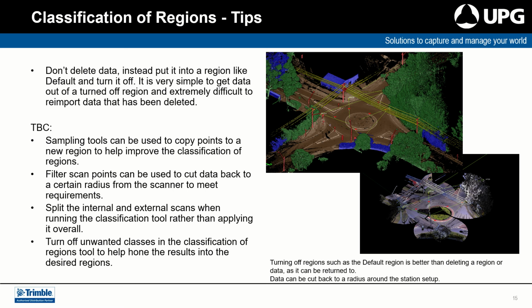Again, as I mentioned earlier, splitting the internal and external scans when running the classification tool is recommended rather than applying it overall. So that comes into that internal and outdoor classification tool sets. And again, turn off unwanted classes in the classification regions tool to help hone results to the desired regions.